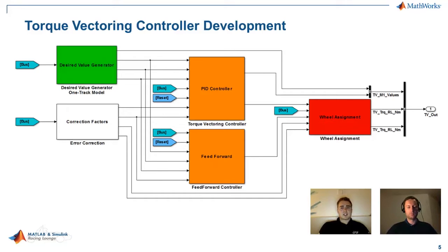And as we talked about in the last slide, the correction factors define the trade-off between longitudinal and lateral controllers. Exactly. This is done in the white box. Here we have the values from the other controllers, which now define a trade-off between the lateral and the longitudinal controller. Okay, perfect. From my point of view, it's a very clear design, and it perfectly makes sense. Thanks for sharing that.